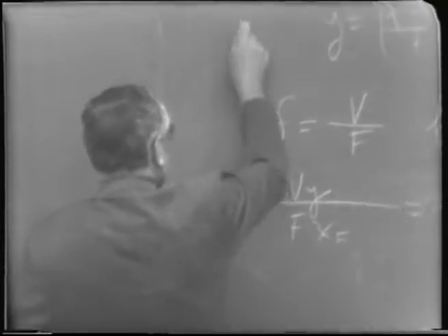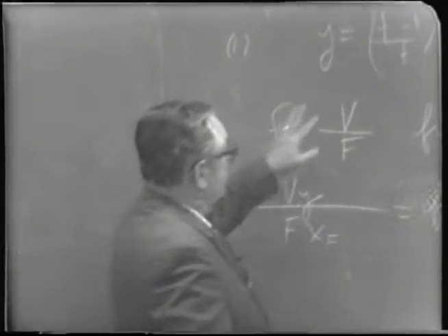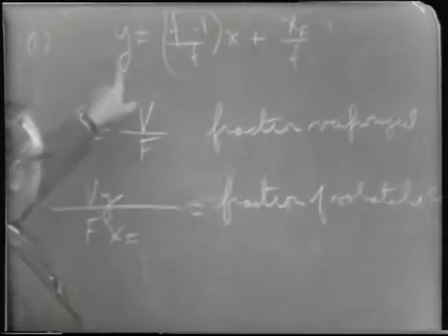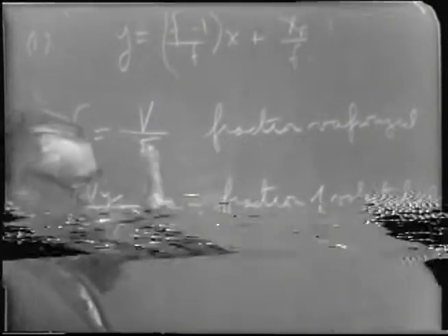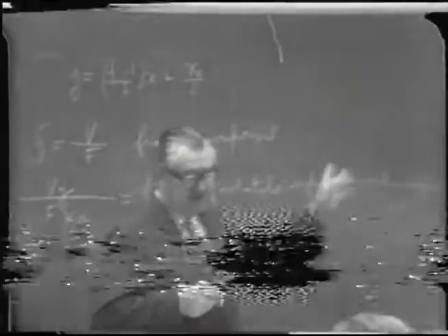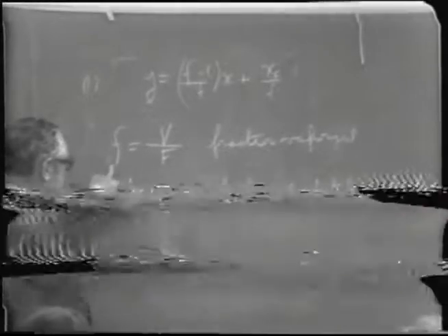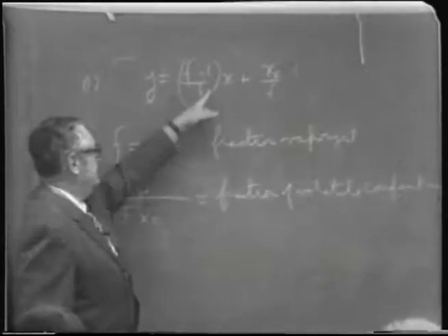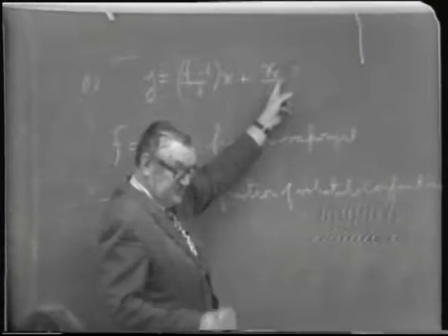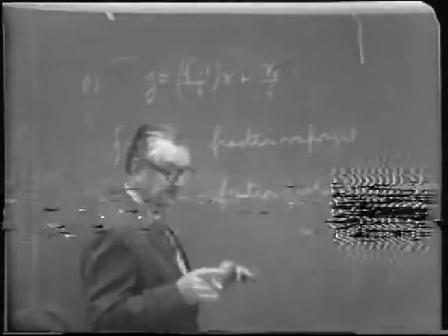But now referring to this equation that I've just written here, this relationship, that's a plus sign, if we're considering a situation whereby we have a stated fraction vaporized, well, of course, f, the fraction vaporized, is a constant term, and then this is a constant, and the feed composition is usually stated as a stated condition, so that's a constant.